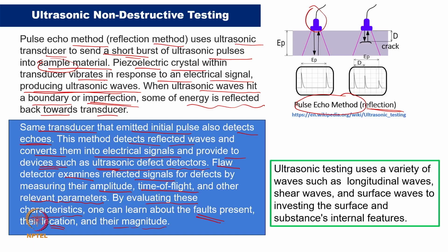It is not that we do not attach the sensor. Even if there is a slight gap, we still need to smoothen the surface so that discontinuity can be minimized, otherwise our sensor will get all the noise related to the top surface. It may be because of surface roughness, some sort of dirt, or some sort of soot formation on the surface. So, we will be getting all bad results. To avoid that, we require surface preparation.